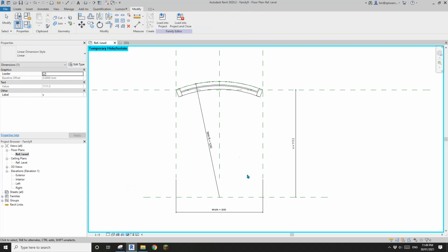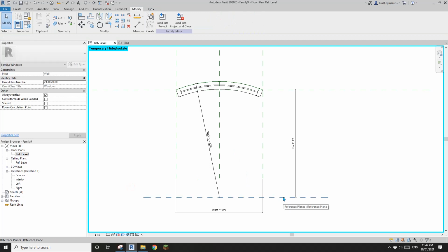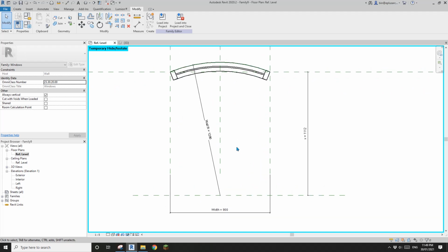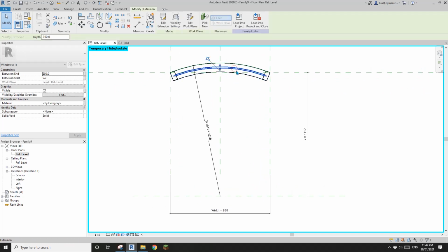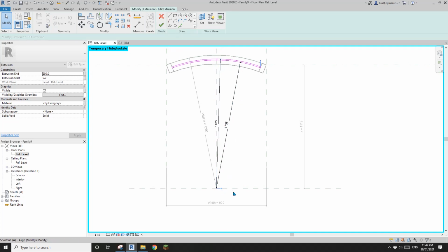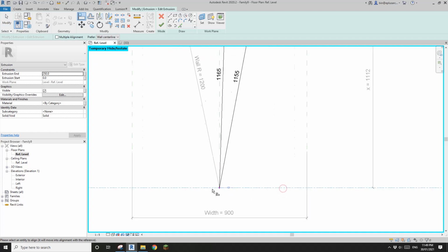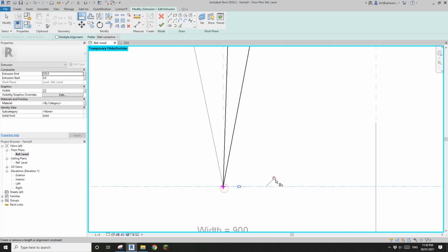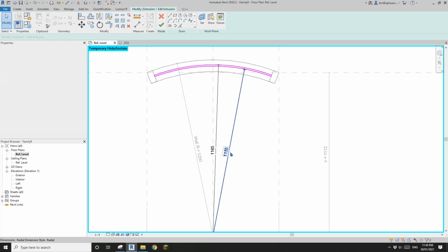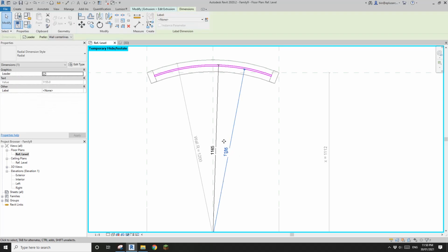So now we have this reference plane. We can lock things onto this reference plane now. So let's go back to this glass, edit extrusion. See this 0, align, pick this reference plane and pick this cross lock once again, because there are 2 arcs there. So okay, all good. Now we just need to give a formula to these 2 radius.